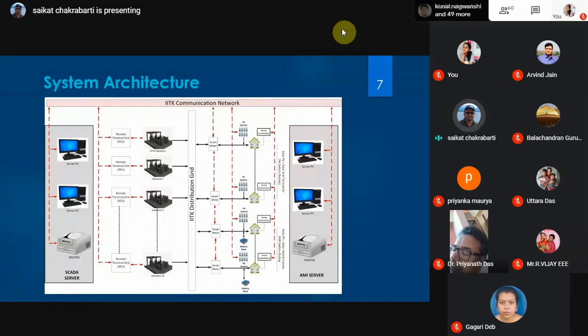One thing, this is our SCADA, and let me put my specs. And these are the substations, RTUs, smart meters. In the control center, we are getting data from different domains. We are getting data from RTUs, smart meters, home automation systems, and even from the solar PV monitoring system. The inverters are communicable inverters. So we are getting data from all these four components in our control center.